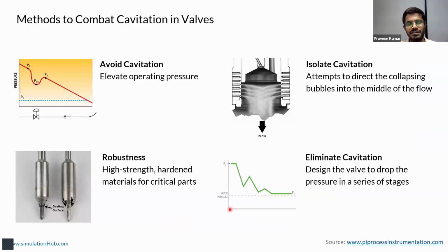One is to avoid cavitation by elevating your operating condition, the operating pressure. So you're operating at such high pressures that you're far away from your minimum pressure, or the vena contracta pressure is far away from the vapor pressure. So there is no risk of cavitation.